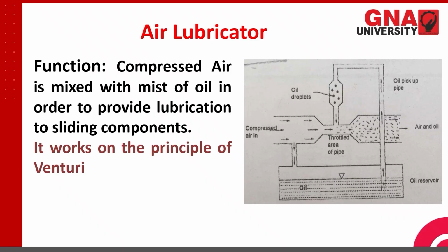So this is the working of this pressure regulator. Spring force can be adjusted with the help of the adjusting screw. Air from the high pressure chamber is allowed to enter the low pressure chamber against the spring force by moving the poppet assembly to provide the constant outlet pressure.